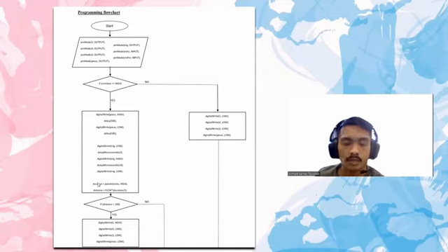And then for this process, there are 2 formulas: the duration is equal to pulseIn equal high, which indicates the duration of the echo sending data through to the Arduino, and then the distance is 0.034 times the duration divided by 2. For this process, it is triggered to the formula for the ultrasonic sensor.